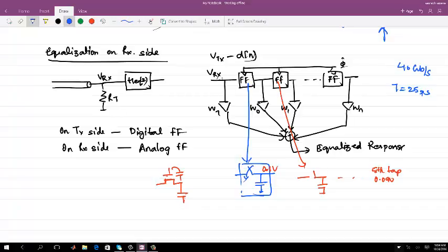And the other thing you see, right, is that this is a sample and hold circuit. So clock to Q delay very much depends on what the voltage at the input is, because resistance depends on the voltage. Resistance of the switch depends on its drain and source voltages. So the clock to Q delay will vary. So clock to Q delay is in question.